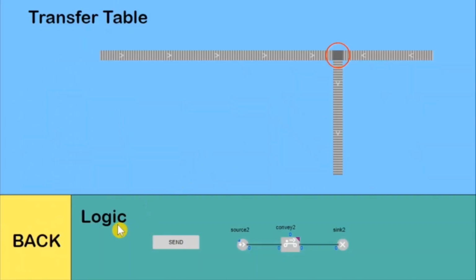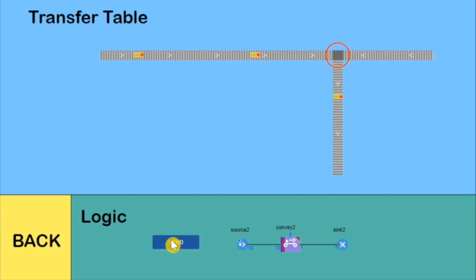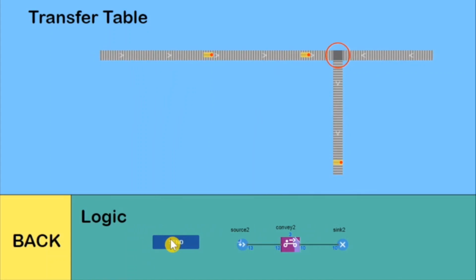Transfer table. Transfer table is the space markup element that is used to define transfer tables in the material handling models. Agents passing through it keep the current orientation in space. Once placed on a conveyor, the transfer table divides it into 2 independent conveyors working in the same conveyor network. Transfer table may connect up to 4 conveyors at right angles. Transfer table has its own transportation speed, and the time required to switch to another conveyor can be defined by the switching delay parameter.